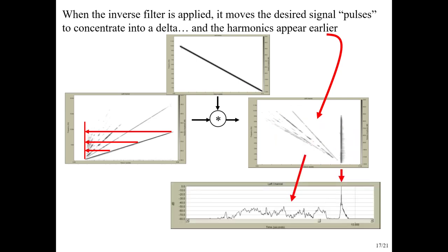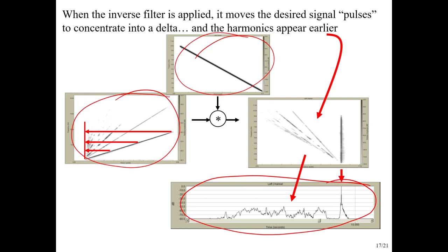So this is beautiful. If we think about converting this back into the time domain, but remember, this is not how we do it. I'm just visualizing it this way. We literally just take the output of the system after we've put the linear sweep in and convolve it with the time reversed sweep in the time domain. This is all done in the time domain. And then we get this. And so this part here is coming from this part. That's just the linear part of the system. And so that's our impulse response.